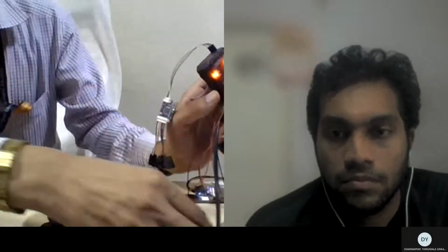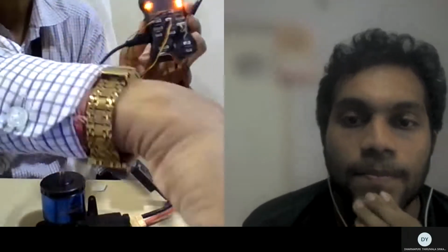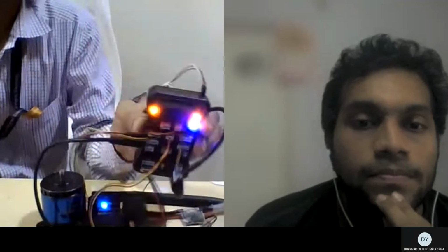So I've taken one autopilot system. Okay, I connected it with USB to the PC. So this is one flight controller, like you can go with the Pixhawk basics. They have given the rails. You can count 1 2 3 4 5 6 7 8 9 10 11 12 13 14 15 16 channels. Hence maximum you can take 14 outputs from this, and 2 reserved for the inputs.